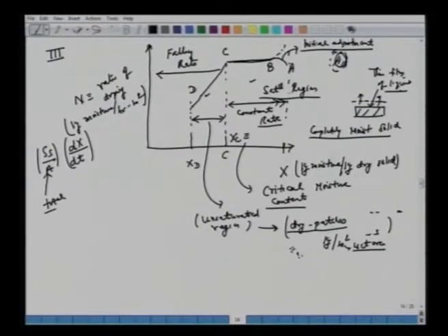So we have saturated region, unsaturated region, constant rate, falling rate. Go back to this now, because earlier when we measured x versus time, there was one more region where the drying rate has gone very, very slow. So you will expect some other rate, it will fall like this, when it has reached x star or xe. This we define as when the solid has reached equilibrium concentration. So this is also the equilibrium concentration.